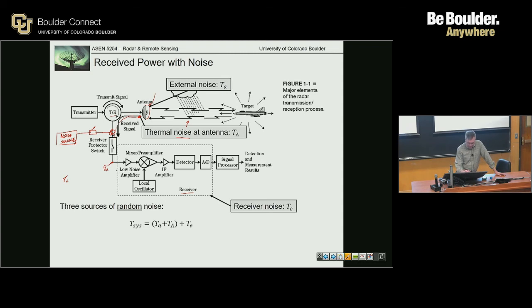So the noise figure, the components in front of the LNA add up, which implies that they add noise, or not so much that they add noise as that they attenuate power signal, because signal's coherent, not random. It's a very confusing concept that I can't get my head around. It doesn't add noise power. And I can't figure out why it doesn't, because the components are not at absolute zero. Right. So they're affecting the.